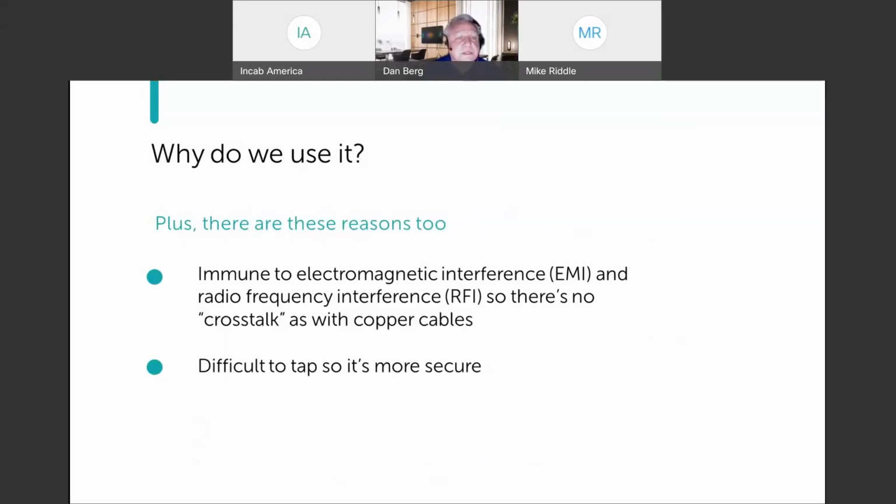Another important issue is EMI resistance, or immunity to EMI. Fibers are insulators. No electrical current flows through them. In addition, the electromagnetic wave inside the fiber is trapped, so none of the signal leaks out during transmission. The ability of the optical fiber to isolate itself from the environment allows us to pack numerous fibers inside the cable with no crosstalk.